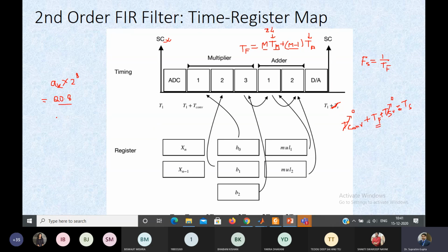But when you go for IIR representation, some coefficients are integers, like you have seen 1 to 1 in the numerator. So you need to find the maximum value of that coefficient, and you need to find the QI. And obviously QI for this case is 2. And so your format should be QI dot QF, that should be 2.6 format in our case. And if that is the case, then your fixed point computation will produce a result in 2.14 format, and from there you will get 2.6 format just by truncating it.